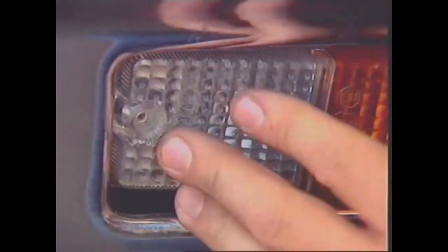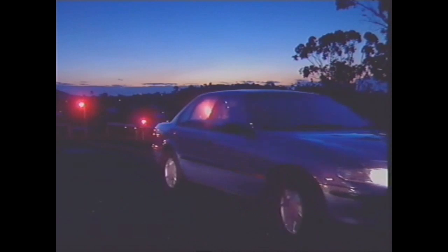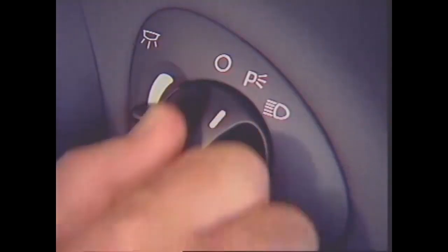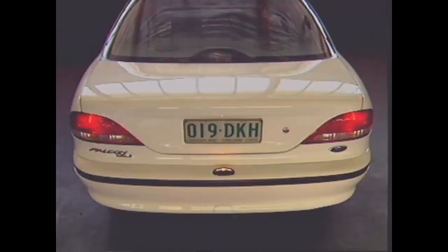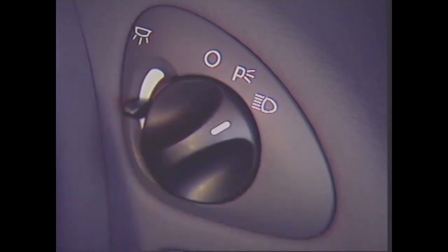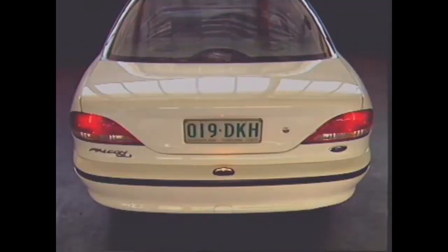The park lights, sometimes called clearance lamps, are located at the front of the vehicle and are used at night time when the vehicle is parked on the side of the road. They use low wattage bulbs and may have a lens or diffuser that makes the emitted light widespread. In some cases, the park lights are incorporated in the headlight assembly. The park lights operate when the light switch is moved to the first position. For safety reasons, the park and tail lights continue to operate when the light switch is moved to the headlight position. The bulbs are connected in parallel with each other.